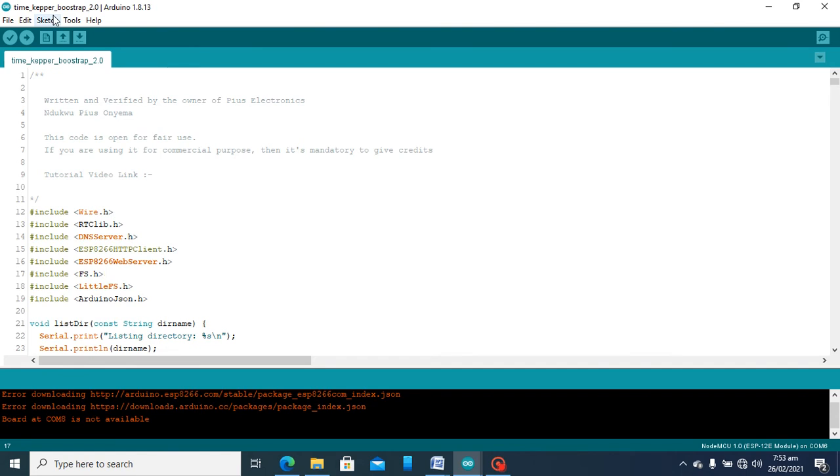When I open the delete page, the JSON file is sent from the home page to the delete page. Whenever I delete something, it deletes that key, the JSON value, in that page. When I'm done, it sends the JSON file back to the Arduino. The Arduino now uses that and updates that file in its file system. So it updates the period timetable in its file system, and it's now updated with the new file and the new time.